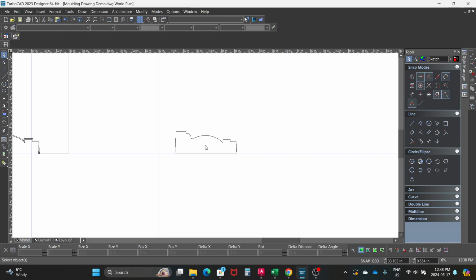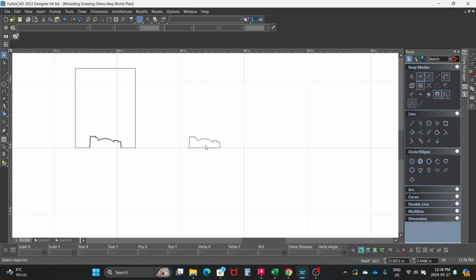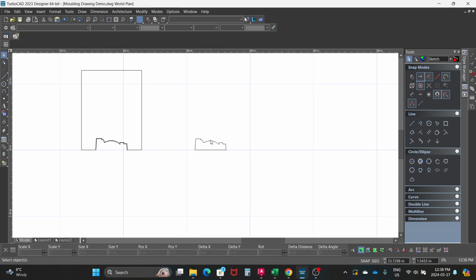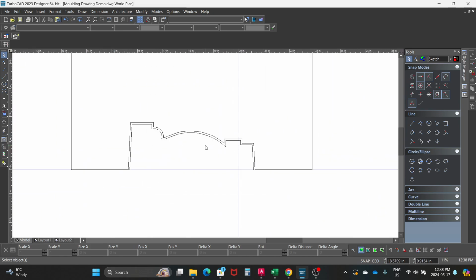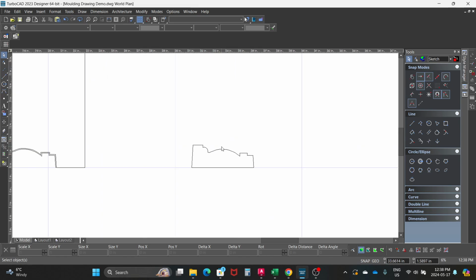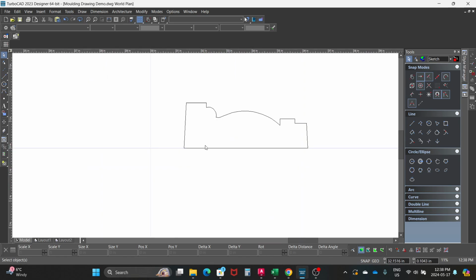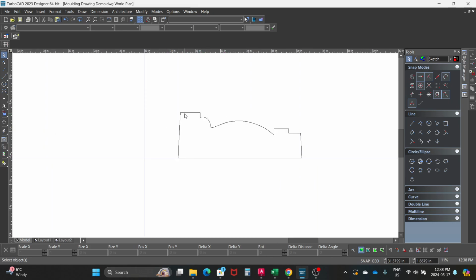So now if I cut this out on the CNC Hotwire foam cutter, basically we wouldn't get the exact right shape, because although we drew it with the 1/16 of an inch gap here, if we cut this out, the foam burns probably a 32nd of an inch or 0.03 on the top and the bottom and the sides.